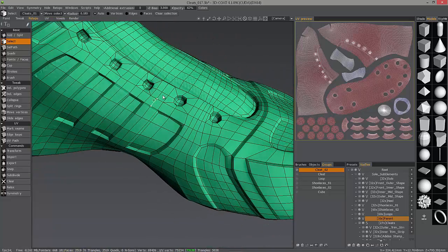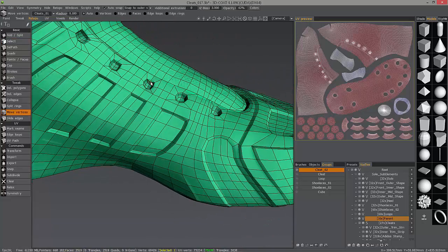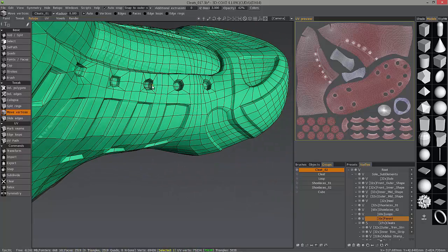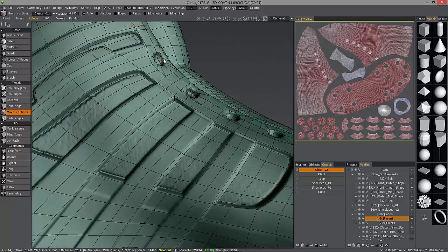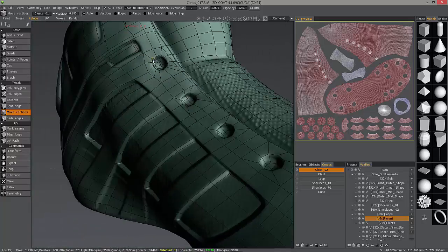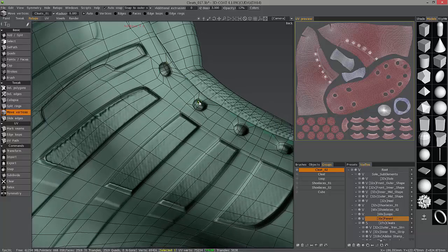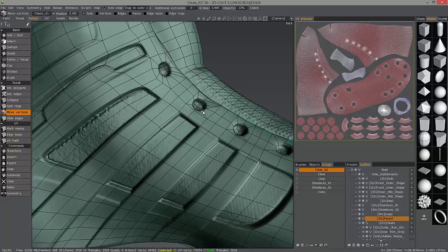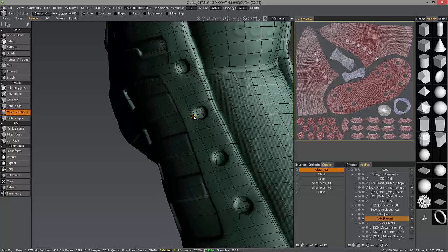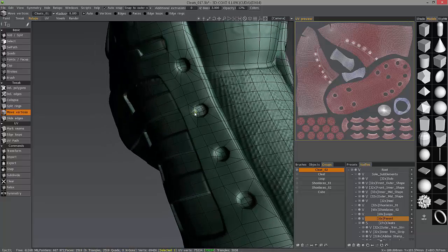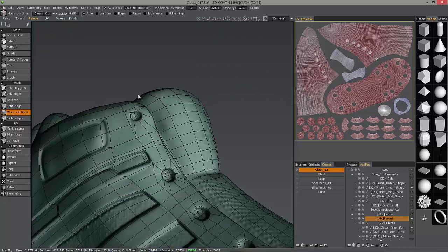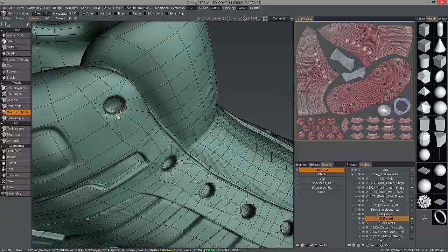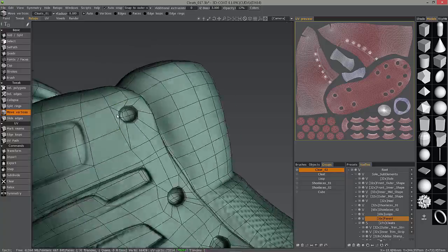I'm now going to go along and just tweak the position of the vertices on each one. Let's now adjust the opacity of the Retopo mesh so we can see the underlying object a bit better. And sometimes you have to be a little bit careful when you're tweaking, because as you move a vertex close to another one, 3D Coat may want to weld it, and you'll see that little red dot indicating that it's going to. So I had to undo once or twice.